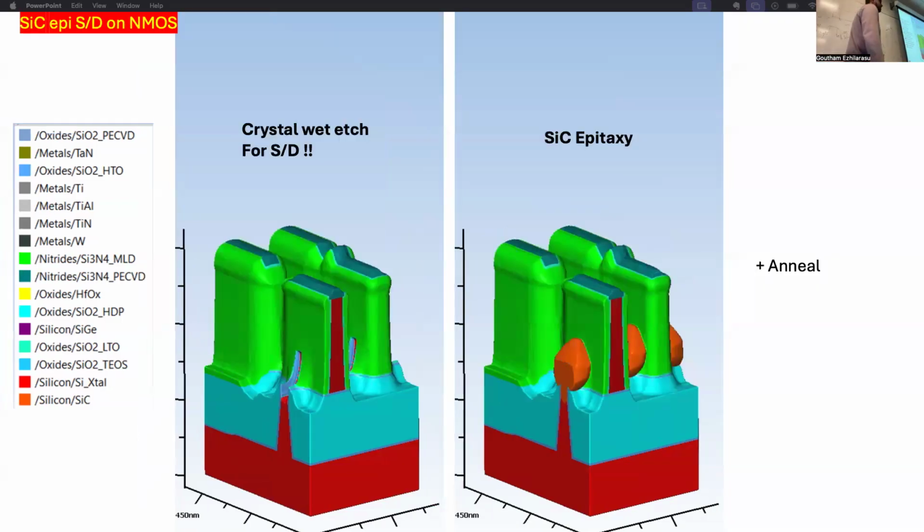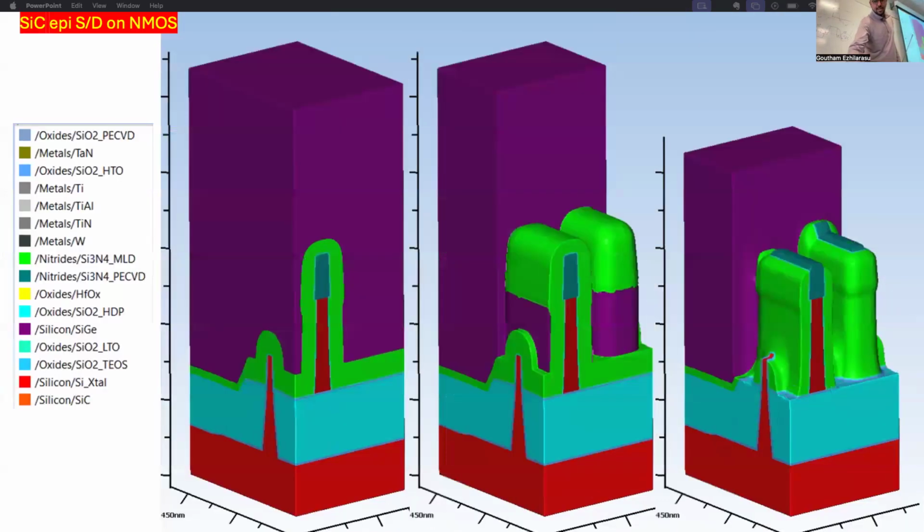How did you super selectively only wet etch that part? Because it's a silicon wet etch. It doesn't etch anything else. See, first what you did is you basically opened up this region, right? This is after silicon etch, and this is before silicon etch. Originally nitride was everywhere, right? Then when I dry etch, the nitride here is gone, and the nitride on top of this is also gone, and it exposed the silicon.